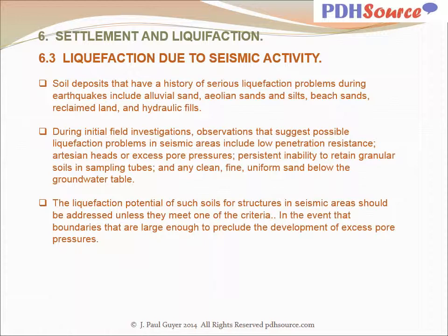The liquefaction potential of such soils for structures in seismic areas should be addressed unless they meet one of the criteria, in the event that boundaries are large enough to preclude the development of excess pore pressures.